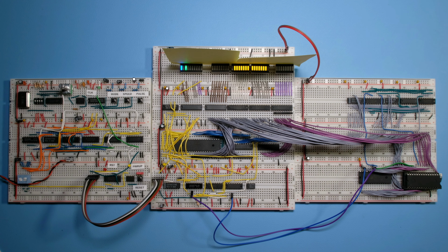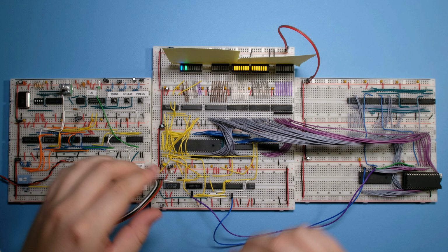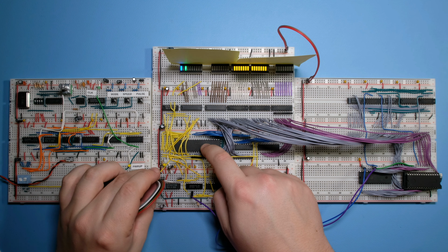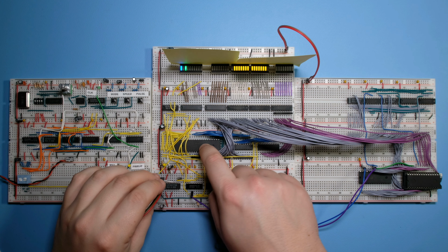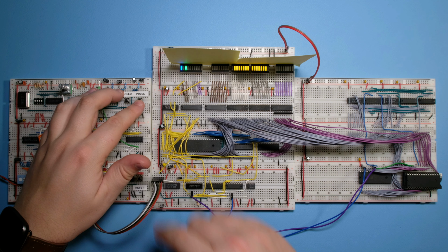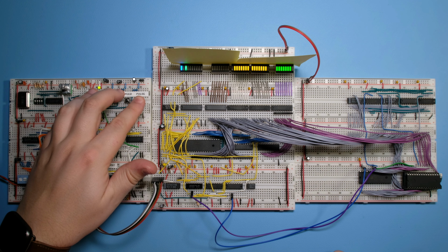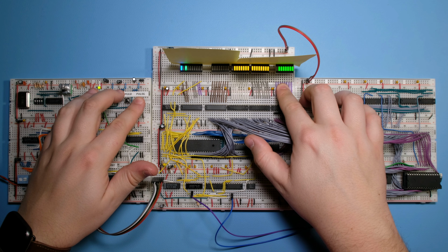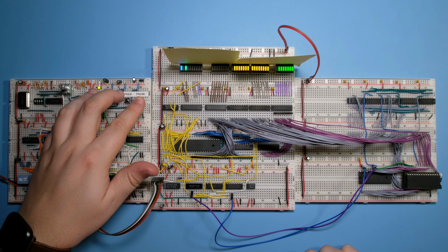And one question I got asked in the last video was, in 16-bit mode, is the CPU actually writing twice to the data bus? So for the low byte and the high byte, and you can see it here. You can see it's writing with the blue LED. I pulse it once to write the first byte, and then it's still writing, and then it gets the second byte. So there are 2 consecutive clock cycles where the CPU is writing in 16-bit mode.